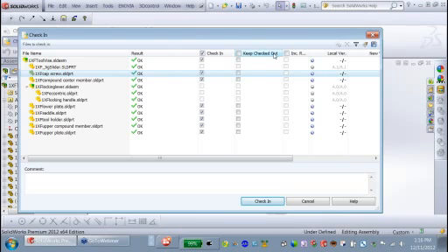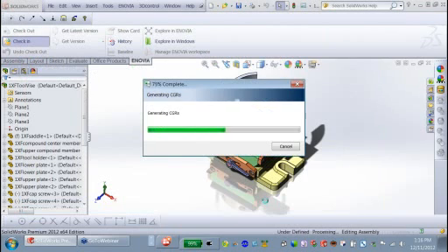I also have the ability to keep checked out, meaning when I check in a structure, I want you to immediately check it right back out to me. This just allows me to back up the data as I'm working, but never leave the environment of the assembly that I'm working on all day long, and share it with all my other teammates involved in the same workspace or project without ever having to close and open SolidWorks over and over, especially if I'm working on a large high-end assembly that takes some time to launch into memory. We'll go ahead and check this structure in.